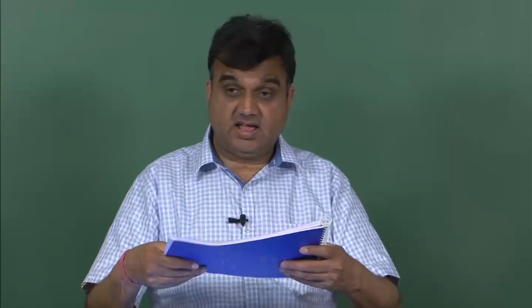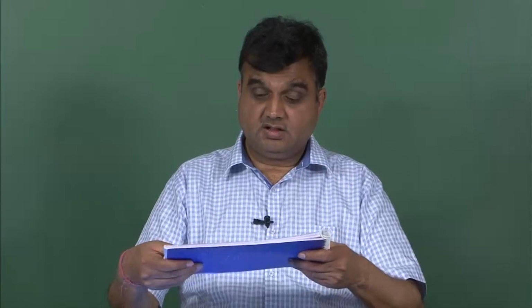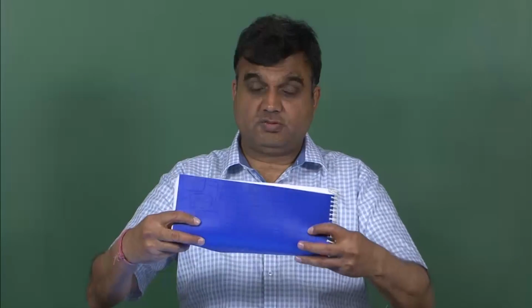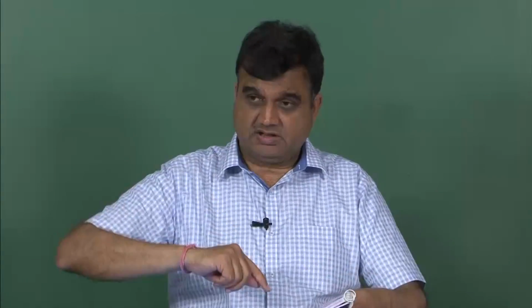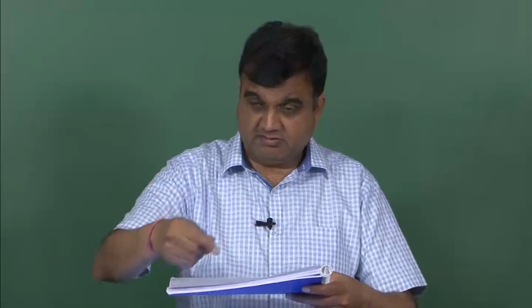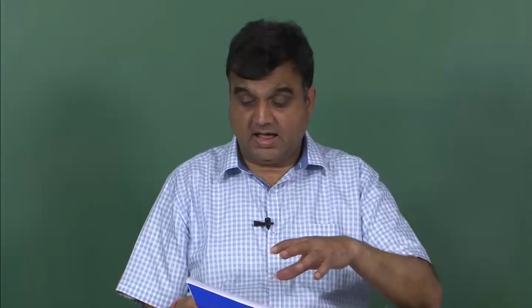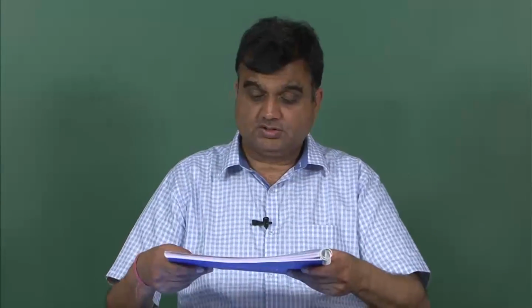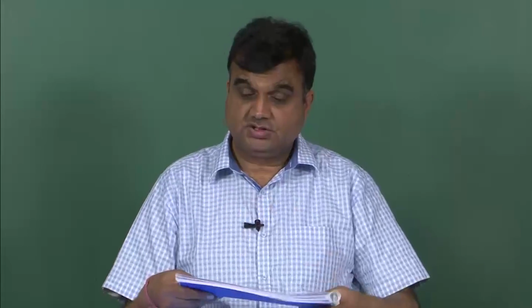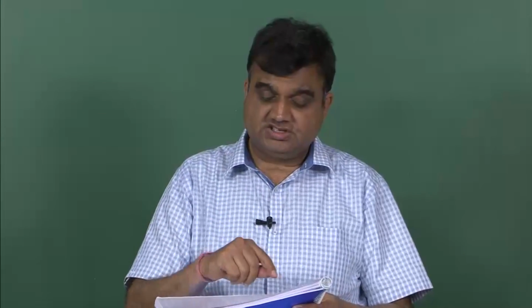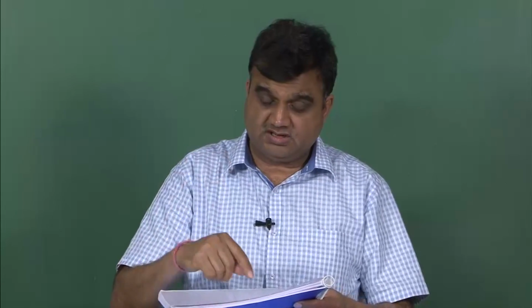Then there is something called kxy, and what is that? This is bending, this is also bending, but then I can also twist it like this. In this case, it has curvature in this direction also, and in that direction also, and it is also a cross component. So the second derivative of W with respect to x and y is non-zero.